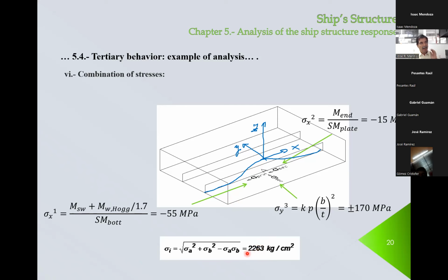221.9. So you multiply this by 9.81 and divide by 100. So it's very close to dividing by 10. So it's about 220. But the thing is that this is very close to 235. So they have done a good design. They are not wasting any material.